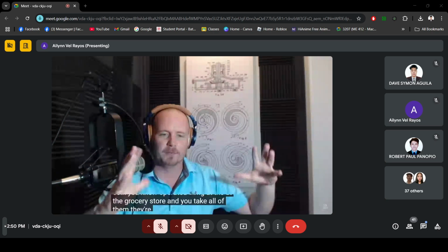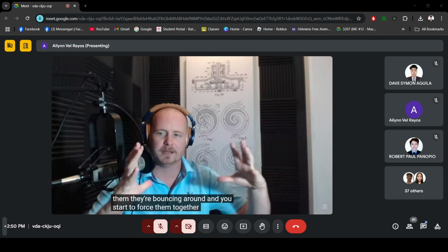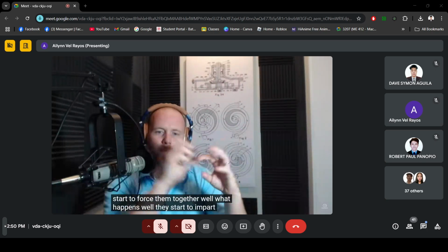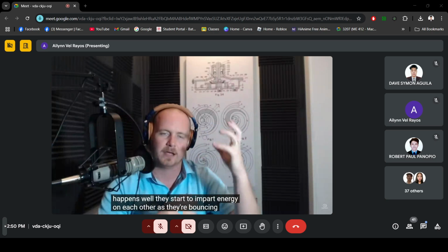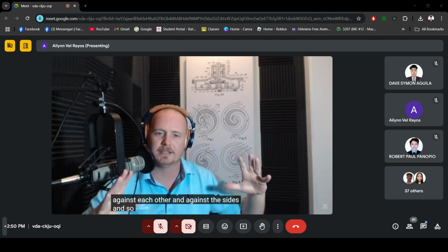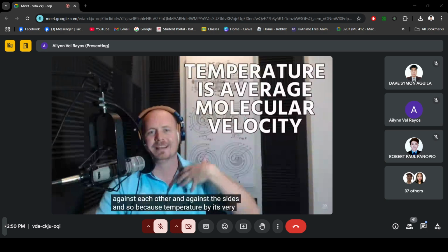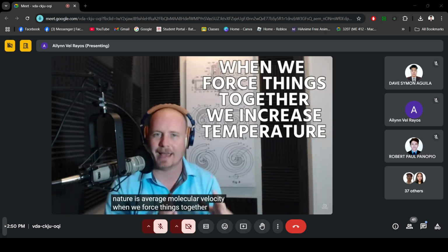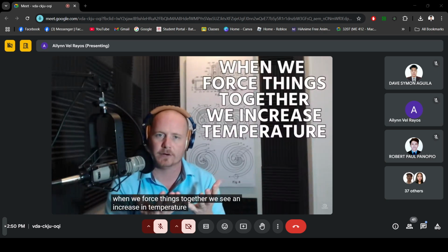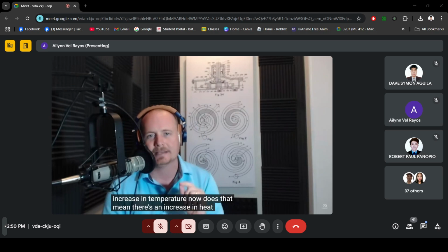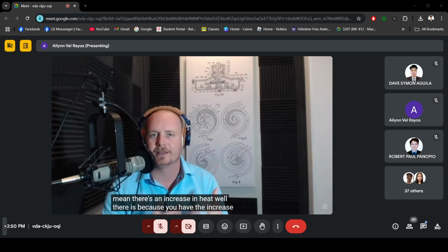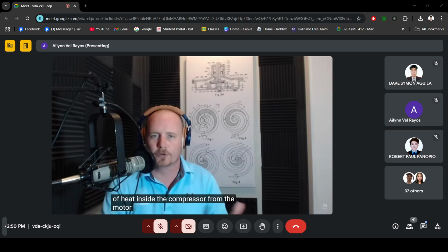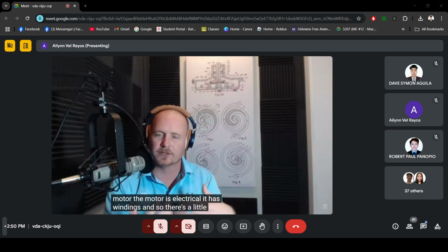And you take all of them and they're bouncing around and you start to force them together. Well, what happens? They start to impart energy on each other as they're bouncing against each other and against the sides. And so because temperature by its very nature is average molecular velocity, when we force things together, we see an increase in temperature. Now, does that mean there's an increase in heat? Well, there is, because you have the increase of heat inside the compressor from the motor. The motor is electrical, it has windings, and so there's a little increase in heat.